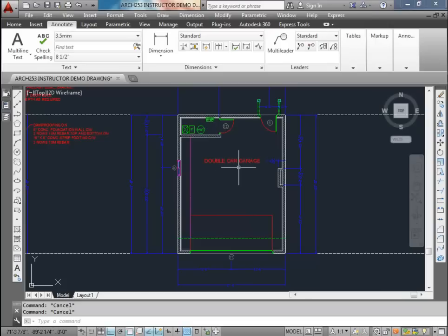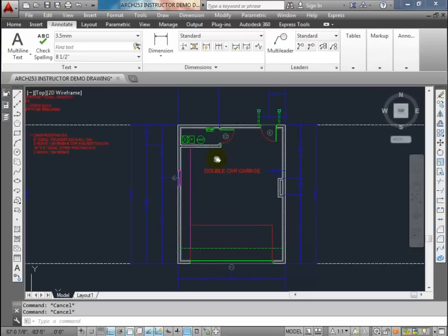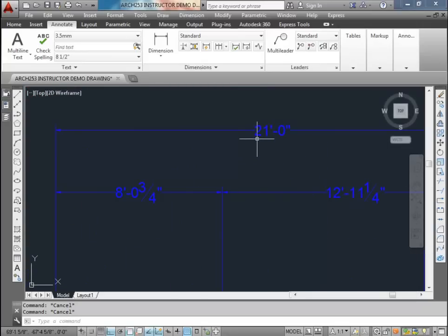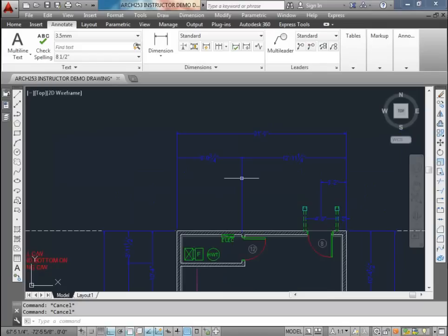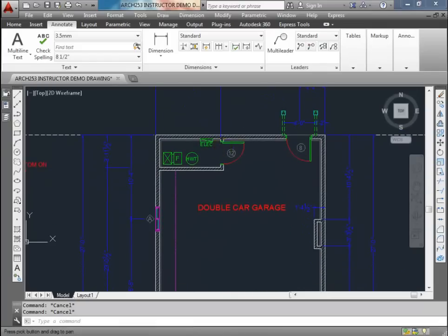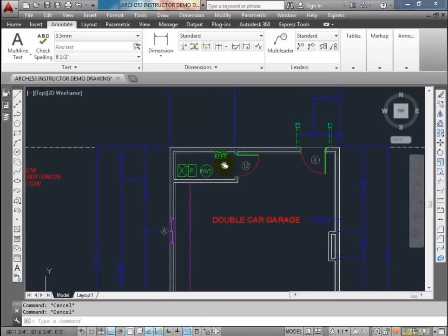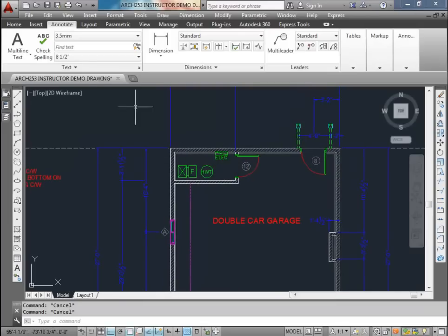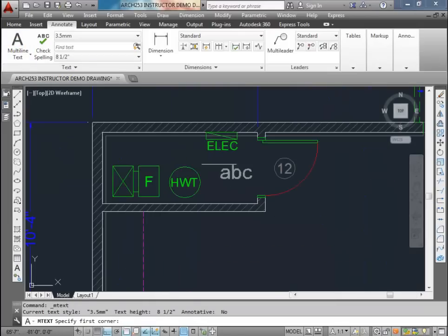We still do have an official title text that we're going to be using, but it's even taller than that. It's 12 inches high, or 12.5 feet high, and 5 millimeters when it finally prints. So the scale that we're printing it at is going to be about 5.5 millimeters, or 5 millimeters approximately. This will be 3.5 millimeters, and all of our dimension style text will be about 3 millimeters, 2.5 to 3 millimeters. So there's 3 different text sizes that we're using in this particular drawing. We're also going to use this same text style for the mechanical room, if we can fit it in here.